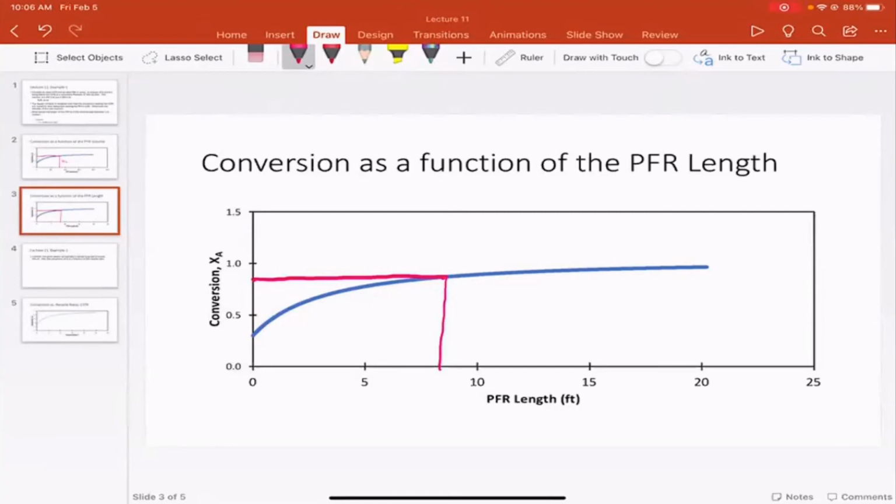So in that problem, what we tried to do was to show how two reactors can work in series. One of the things that I really want to stress is when you're thinking about the second reactor, don't forget that you're not at the initial concentration. You're at the concentration that's coming out of the first reactor as you enter the second one.